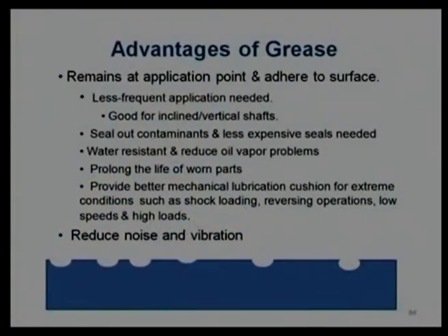This sketch shows, I am just assuming, an initially solid surface, and when the solid surface develops pits, maybe due to fatigue loading, then naturally there will be vibration. If any rolling element passes over the surface, it will come with some sort of contact and non-contact, contact and non-contact. That means the stiffness will be high, then low. When metal to metal contact is there, there will be high stiffness. When there is no metal to metal contact, stiffness will come down. So, there is a continuous variation in stiffness that will induce a vibration phenomenon.